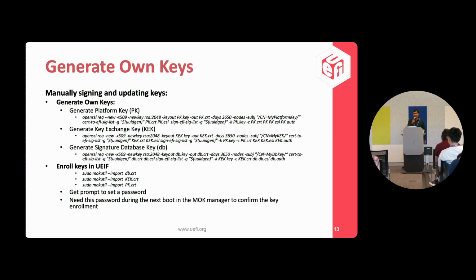Now that we have all these keys available, we have to add them to the database, right? So the third command is to add those files and the keys to the database. After having all the keys and the database available, we have to make sure it gets enrolled in the current existing UEFI framework. And then the next time it boots, it takes those latest created certificates and the PK keys.